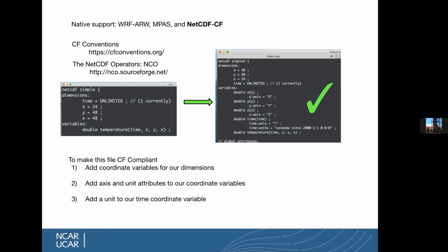So we have an X coordinate variable here that is according to X. And this just defines where each grid point on the X axis is. So it can be at 0 meters, 50 meters, 100 meters. And same goes for the Y coordinate variable and the Z coordinate variable. Below these variables, we can see what are called NetCDF attributes. We've given the axis attribute to X, Y, and Z, defined as capital X, Y, and Z. That allows Vapor to know that these coordinate variables define these axes in space.